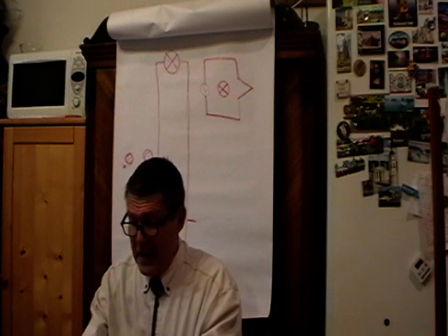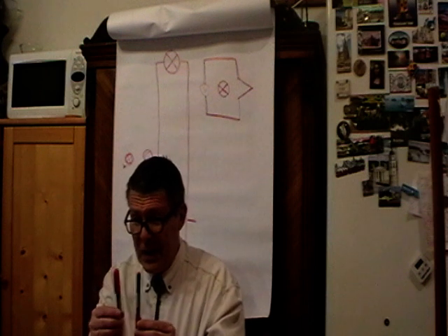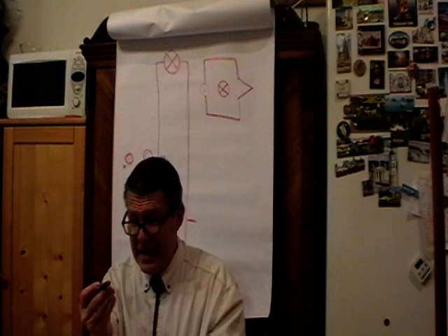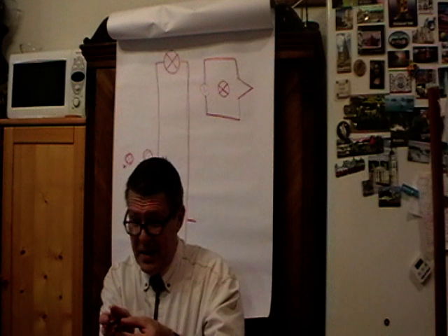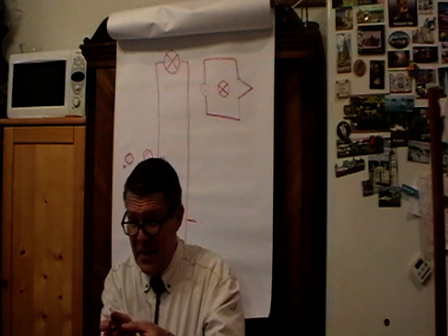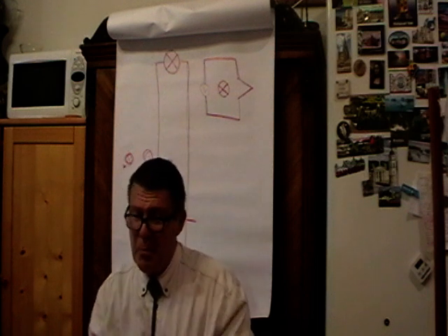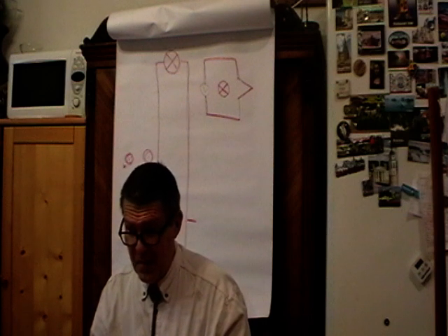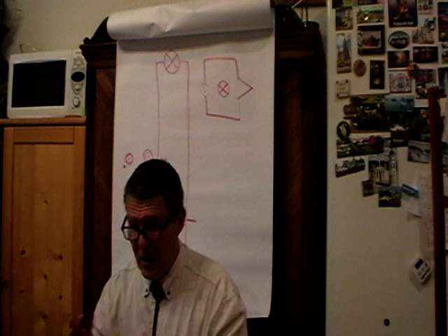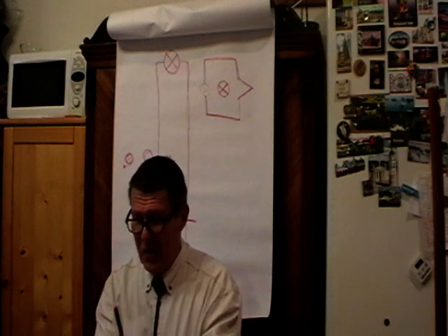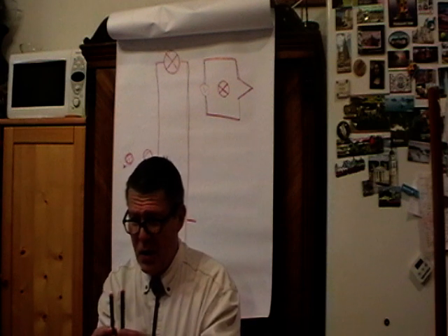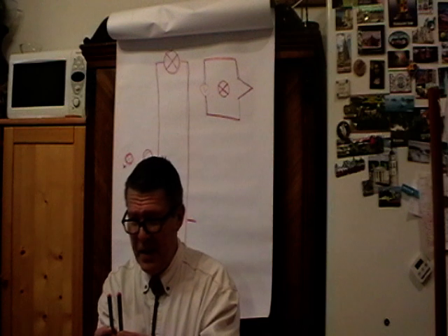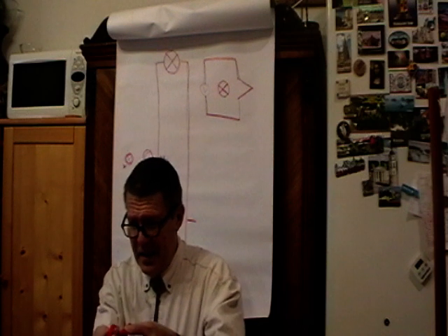Just for a line, for example, consisting of two conductors of this thickness in this distance, I would guess the impedance somewhere to 200 ohms. So a 200 ohm transmission line would be created by two copper rods or sticks that would be this way shaped.